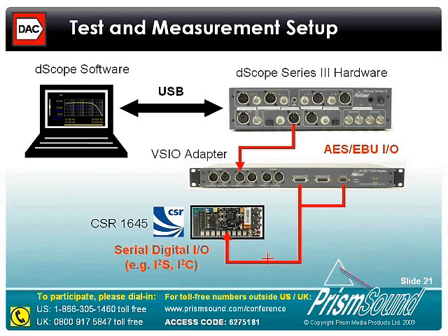The reason for introducing this component is that I want to test just the converter and nothing else in this system. So in other words, if I were injecting my signal via Bluetooth, as in the previous example, I would be measuring the codec and potentially a number of other components upstream of the D2A converter. And actually, really what I want to do here is just measure the converter and nothing else.